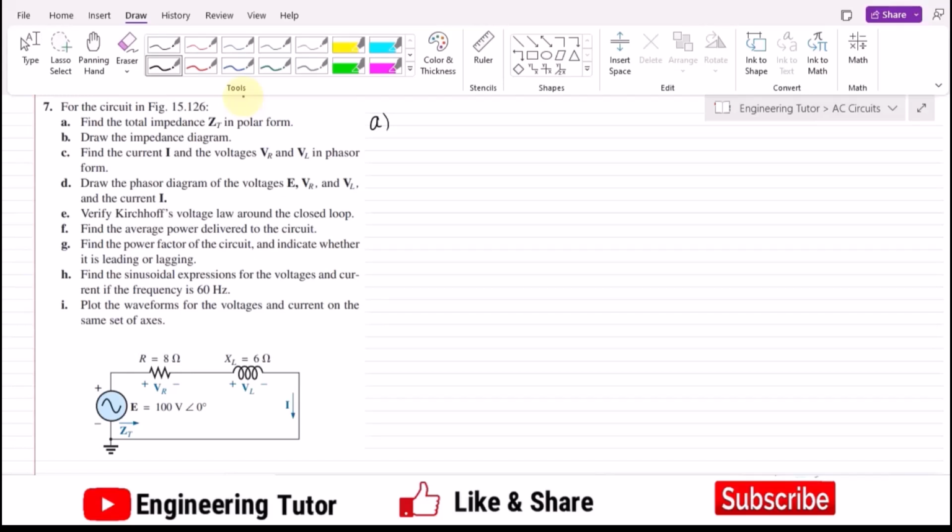So in part A, what I have to do, ZT is equal to the total resistance. So only resistance we have this R, and similarly here we have the inductor, so it has the inductive reactance with which I have to write the plus J, so that's why it will be plus J X of L, okay. So now writing their values, it will be 8 plus J6. So this is now in the rectangular.